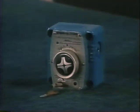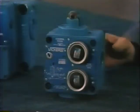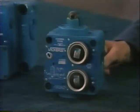The knob on the front allows us to set the throttle opening, and the key is a means of locking the setting. The valve is installed into the system by means of a subplate which has matching in and out porting. Over here we have a feed control panel, which in effect is two flow controls. This package allows the cylinder to have a rapid advance and coarse and fine feed cycles. It too is installed into the circuit by means of a subplate.